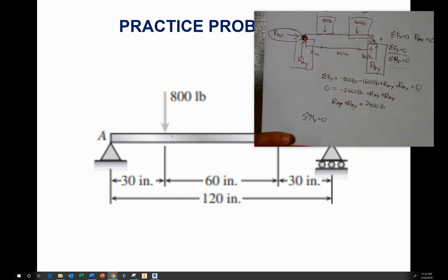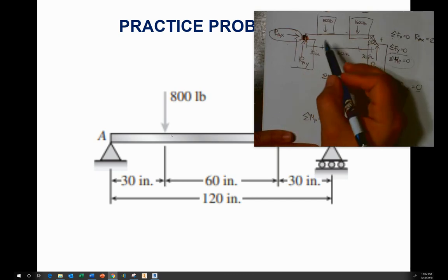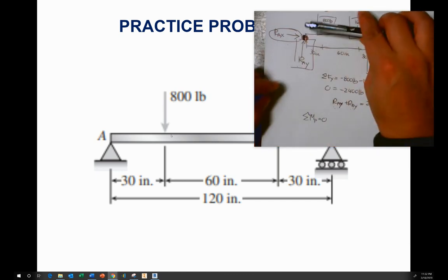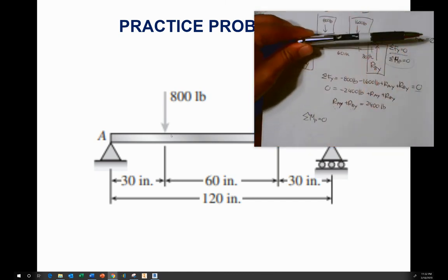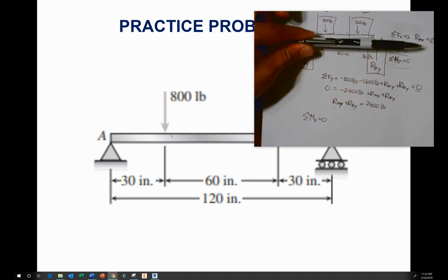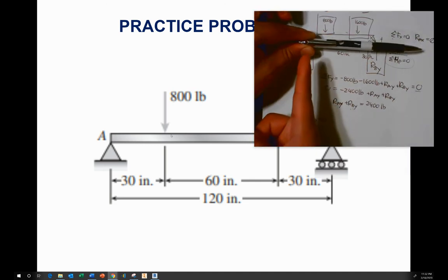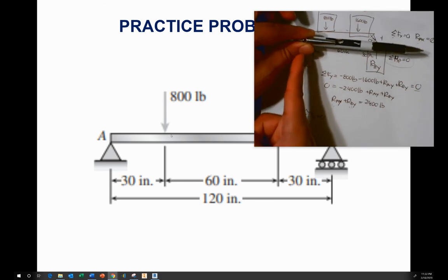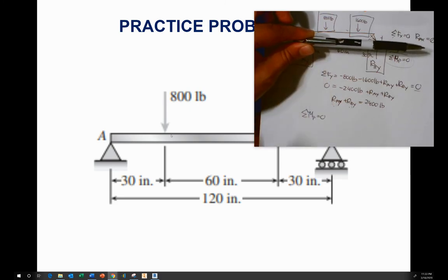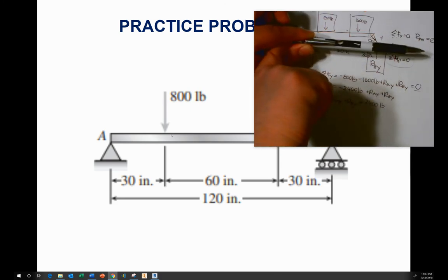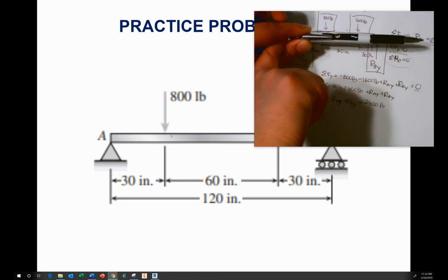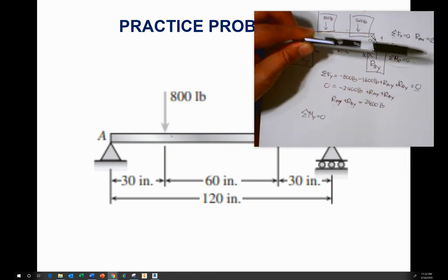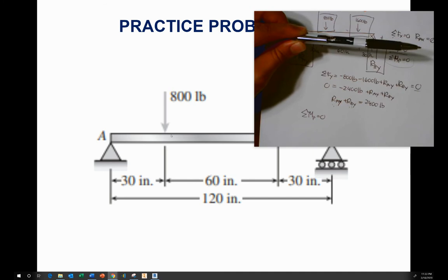And again, what I'm going to do is take the moment created by each of these forces. If I have a pen and I pin it here, and I push up, will that create a turning moment? No, it's just going to push my nail. It's not going to make the pen rotate. If I push in this direction, which I know is 0, but just for point, will this want to rotate? No, it's not creating a moment. It's just creating a reaction force, right?